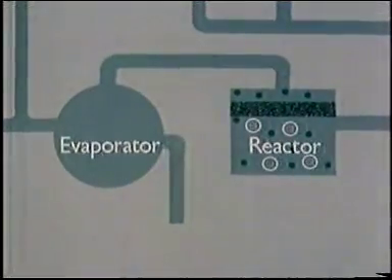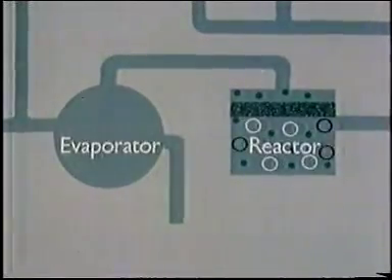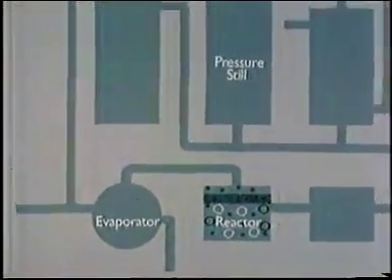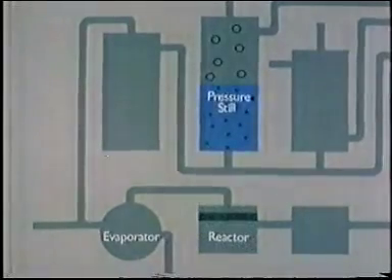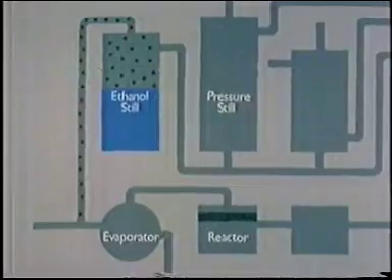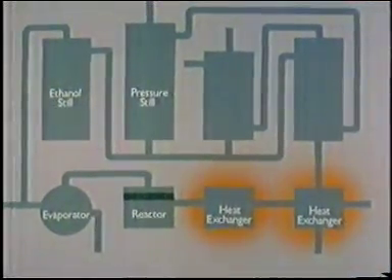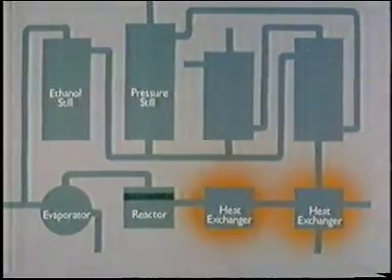What do we want of the products from the reactor output? Well, there are three valuable components. There's the product, acetaldehyde, that must be separated and purified. There's the excess ethanol to be recovered and recycled. And there is heat, put to good use in other parts of the plant. Let's see how the acetaldehyde is recovered.